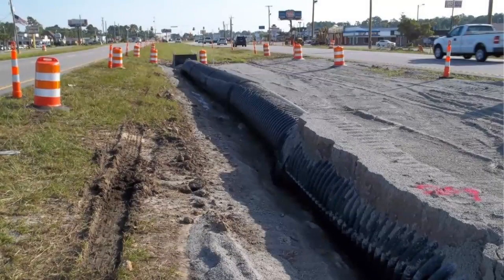And you can notice there sometimes it will lift up so much that it brings up the entire column of material on top of it with it, if you have a lot of groundwater there and a lot of pressure pushing up on it. So this is a pipe that floated up out of the ground there and lifted the soil column on top of it.